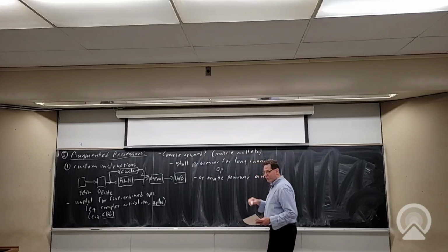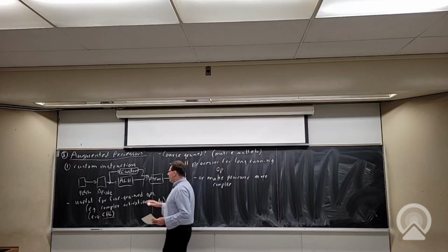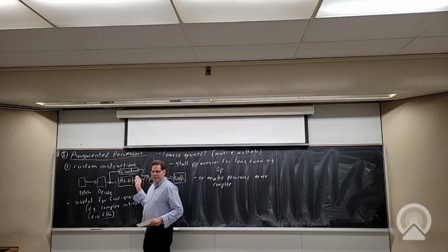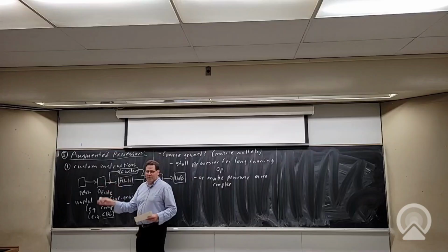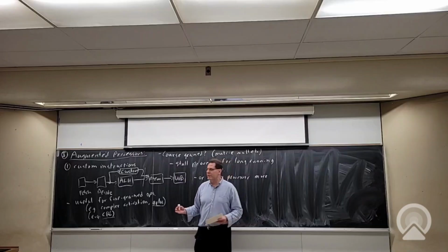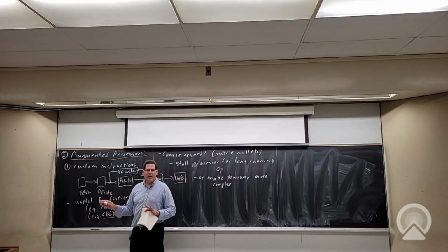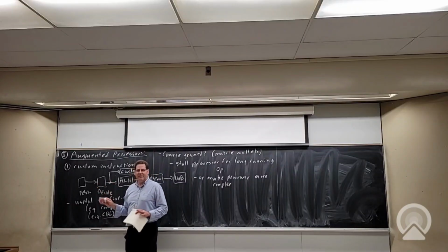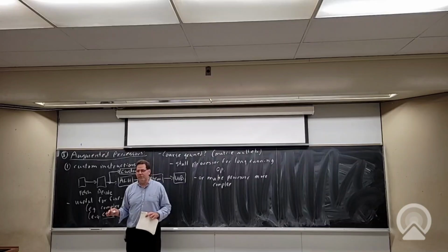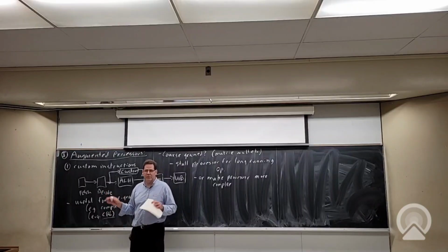Which processor were you using, actually? Okay, interesting. Okay, so maybe they're not stalling. Although if you're depending on this, you may still run out of things to do, right? These processors don't have fancy out-of-order mechanisms because they're too hardware expensive. So if it's not going to stall, you're going to have to keep track of that. Do you know what I mean? Because the processor is not going to keep track of when it is okay to get instructions again. So the programmer is going to have to figure that out.